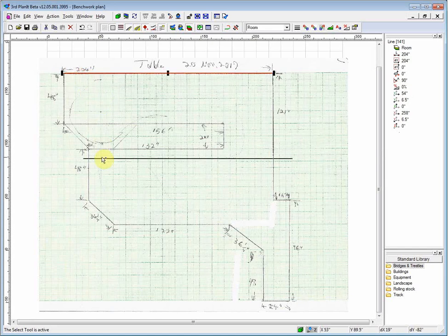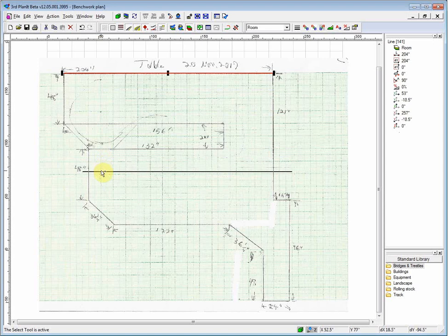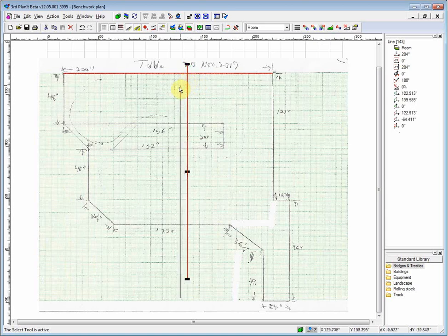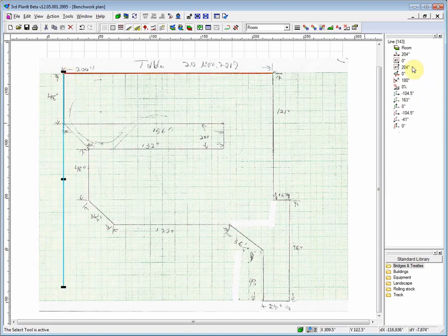It's often good to draw a line just by dragging a copy. If you hold the Control key down while dragging an image, you'll get a copy of the original object positioned where you release the mouse. Rotating it twice, I now hold the Alt key down while selecting it to select at the nearest endpoint, and keep the Alt key held depressed while aligning it. This aligns it to the nearest endpoint of the positioning object. We can now change its length to be 48 inches as called for in the drawing.